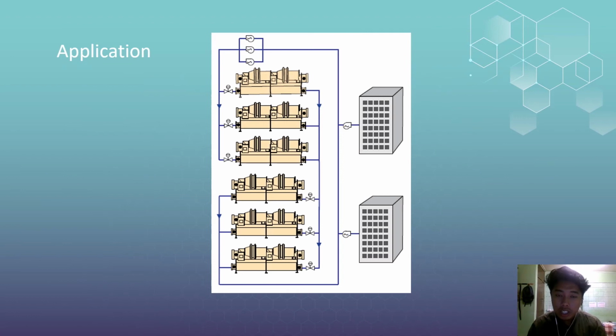So for the next slide, this is our system design. We'll be using 6 chillers to cool 2 buildings. A large chilled water system with 6 or more chillers has different challenges than a smaller system. Examples of this type of system are commonly found in campuses with multiple buildings, downtown districts and mixed-use residential and commercial developments. Creating one centralized chilled water system takes significant foresight, initial investment, and building development with a multi-year master